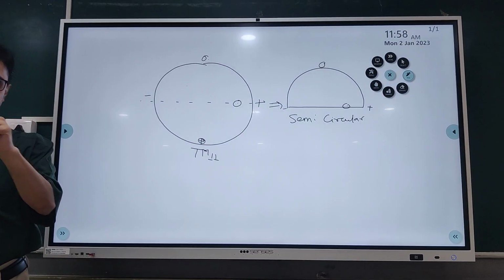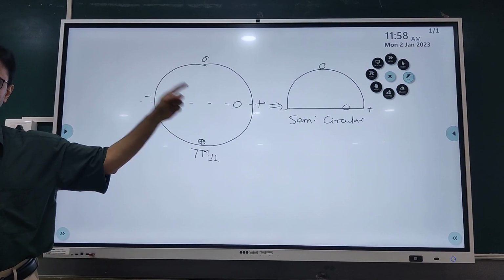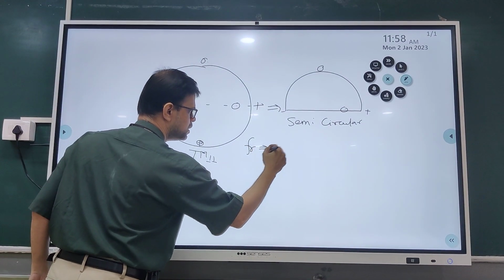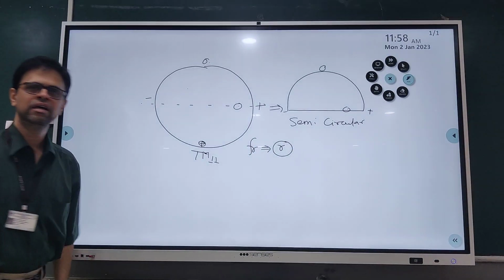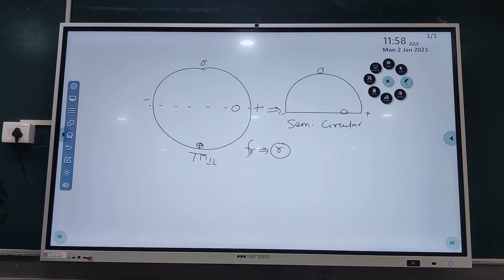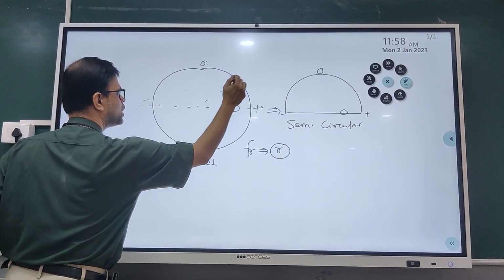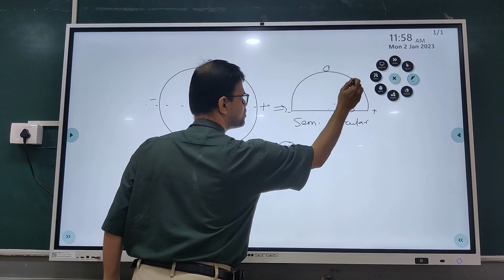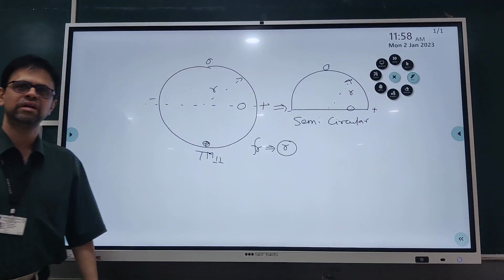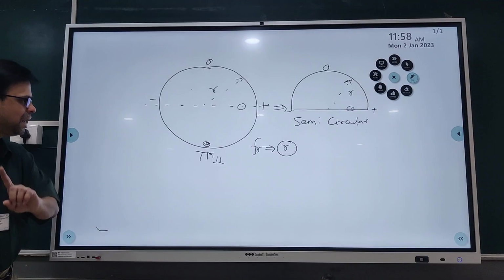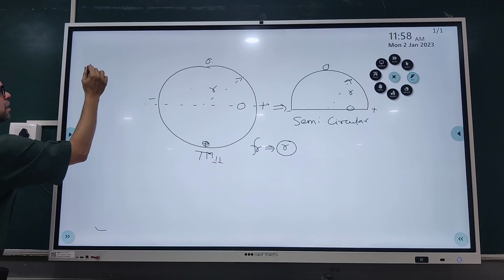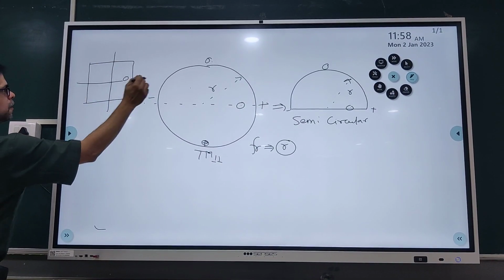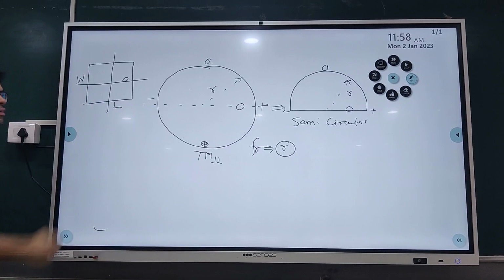The main reason is, in the circular design, the resonance frequency fr is proportional to the radius of the patch. And in this procedure, I am not changing the radius of the patch. Unlike this case, just consider the example of the rectangular microstrip antenna. Here, this is your length, this is your width.